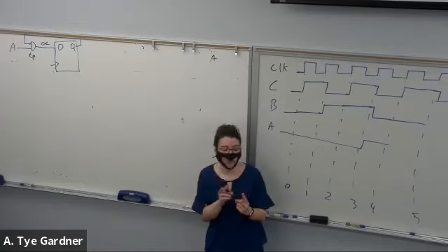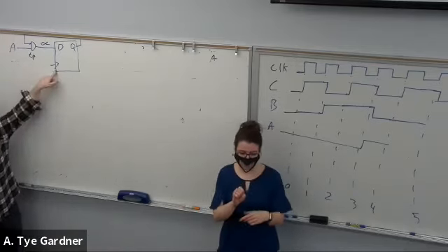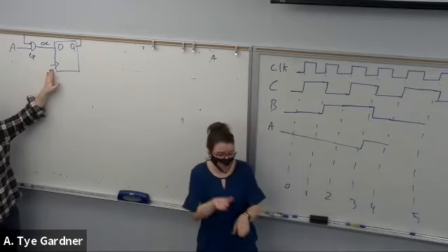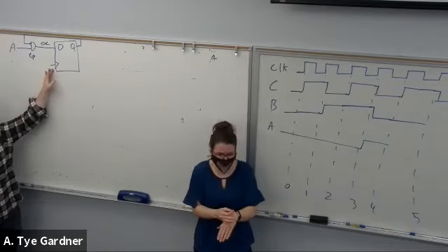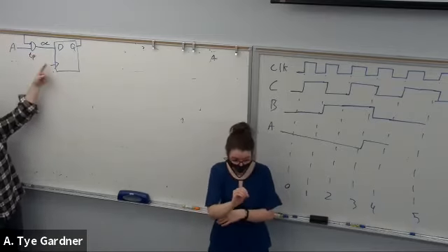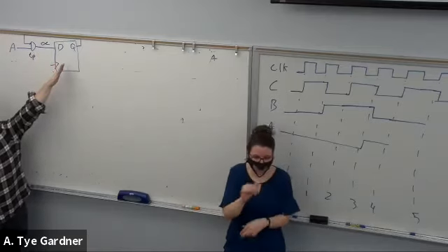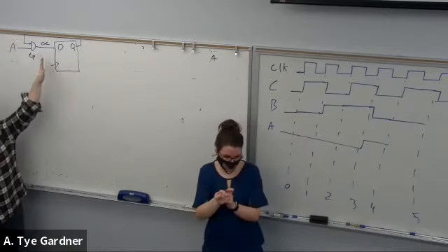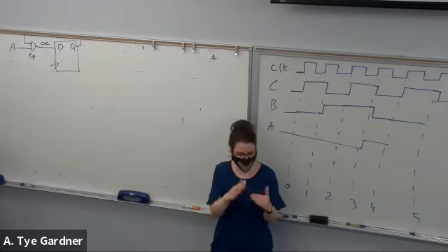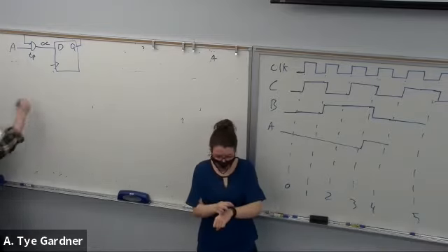You can relate the fastest clock speed that you can do. Because if this is a really slow clock, let's pretend it's running at once per second, and these delays are nanoseconds, there's just no chance of running into an issue of D not being ready when Q changes, in this feedback loop. So what is the minimum time? If it's a really slow clock, we're fine. If it's a fast clock, we can start running into issues.